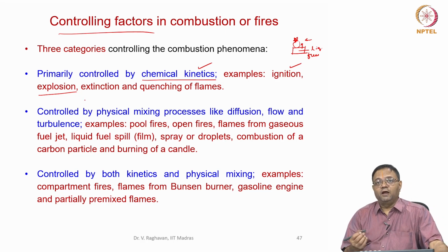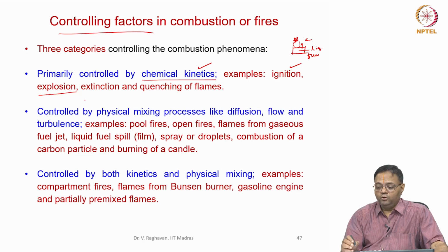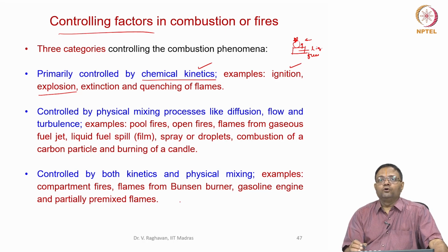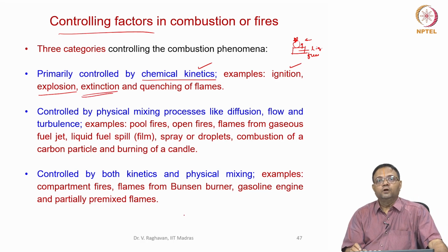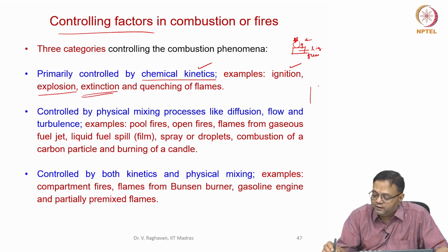Similarly, when the flame is quenching, you will see that the chemical kinetics plays a role in extinction. For example, when the fuel jet is coming out at a higher velocity, I told you that a lifted flame can be formed. So this is the lift off height. This is like a local extinction, correct? Here there is no flame.